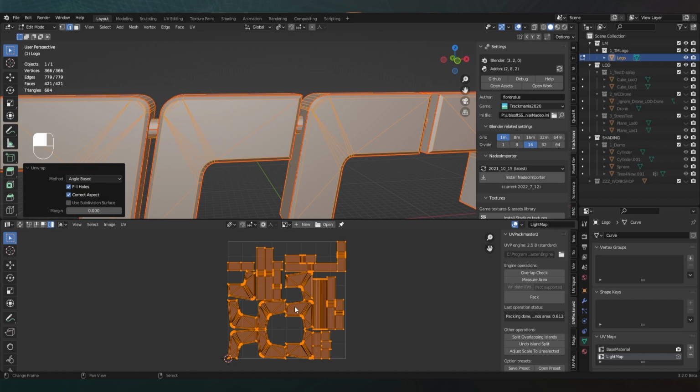Even if it's a small difference, it can at least have some effect in game, especially when the map is very crowded. So we can actually, with a tool, measure the area that is currently selected, that is filled by UV shells, and that's about 58%, let's say 59%.